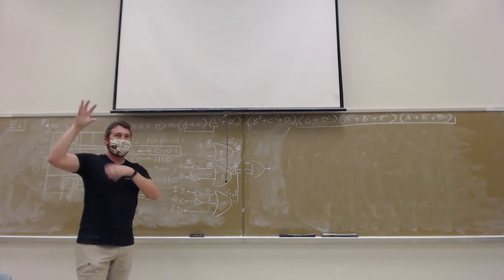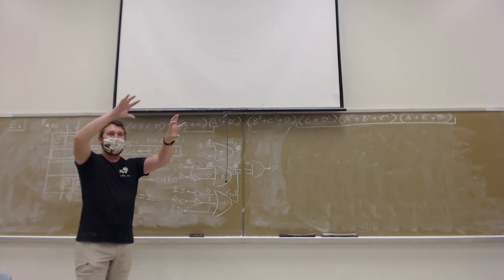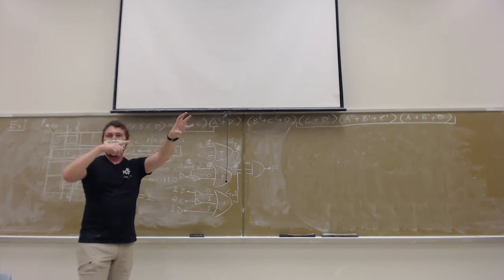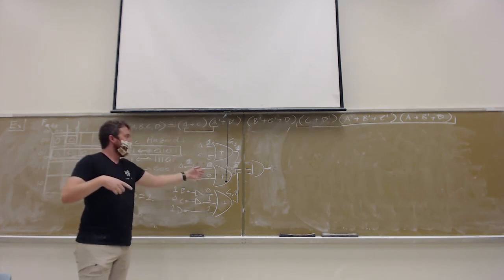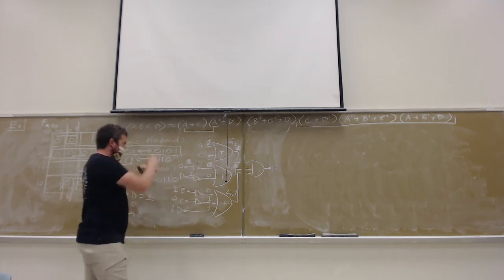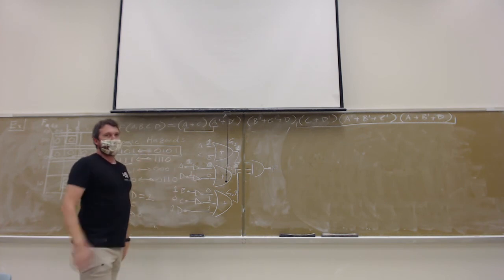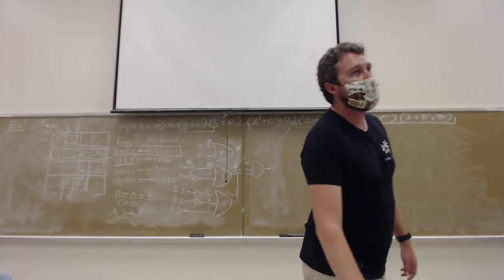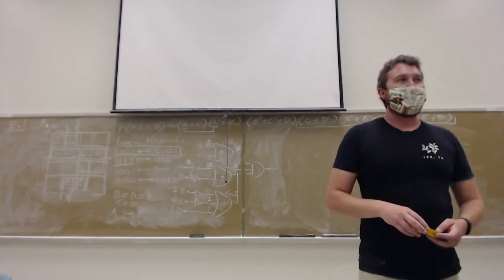If I have two asynchronous functions and I want to do function 1 to the database and then function 2, but both are asynchronous, then you have a race condition, which means function 2 might beat function 1 to the database, in which case your stuff will be out of order. Arguably that's exactly what we're talking about here. The signals are arriving in an order that screws up your output. So there you go, there's my answer: race conditions are the software engineering equivalent of logic hazards.